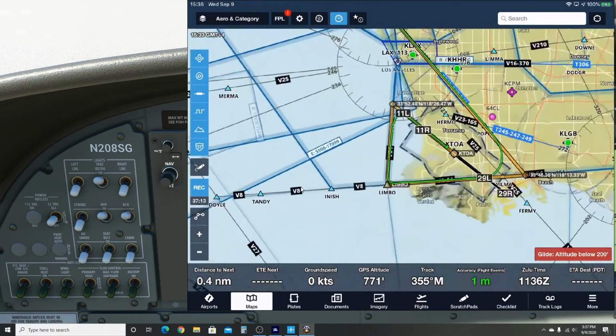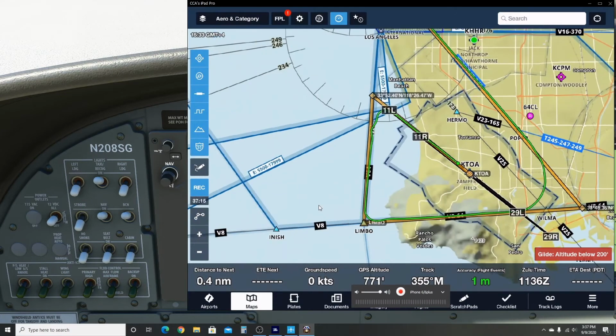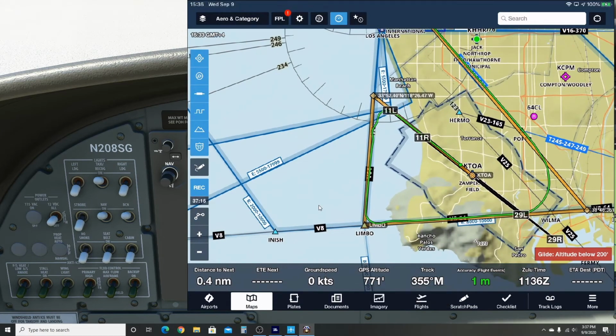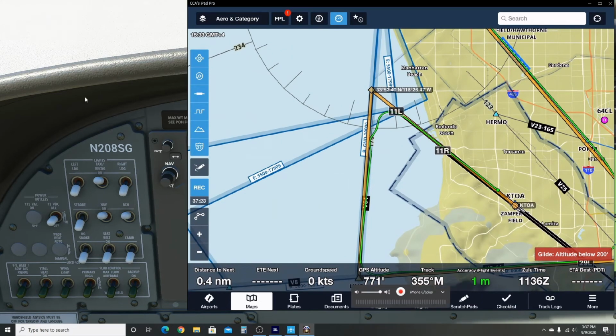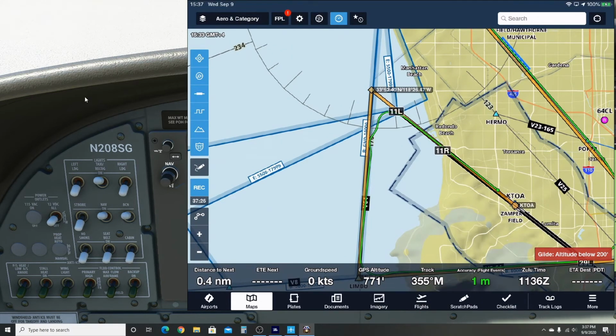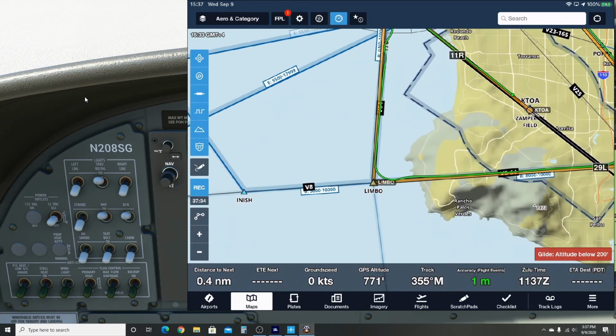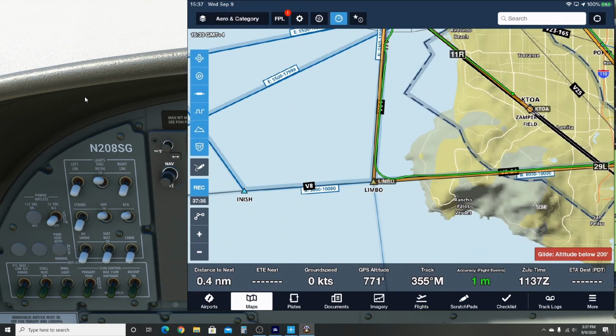Okay, 37 minutes, and now we can do here a debriefing. So I think everything went well. Here perhaps I think, yeah, I was a little bit early to start the turn. I saw the CDI moving, but it was not really that moving, so I was a little bit early there. Then I selected nav beforehand, and it didn't do a very good job, so you have to reselect heading and stabilize things before reselecting nav.